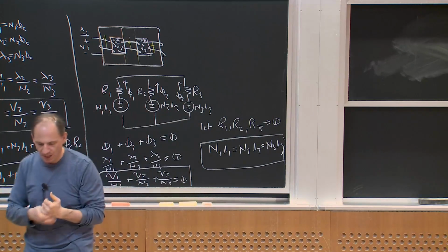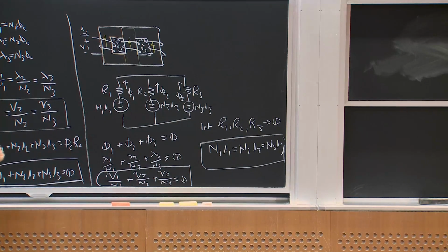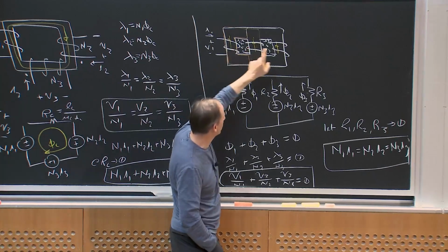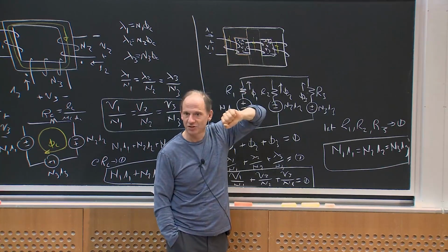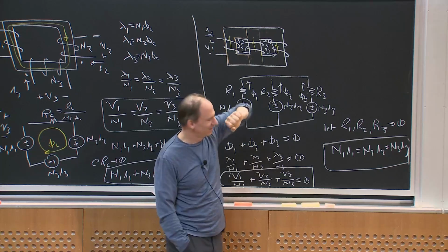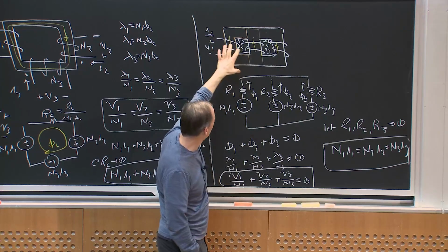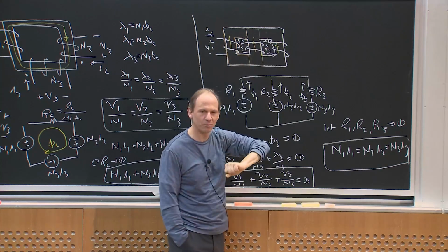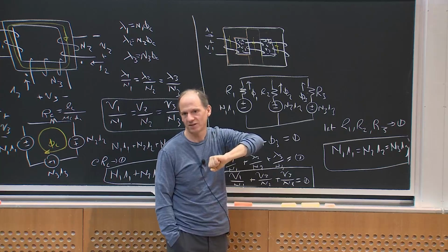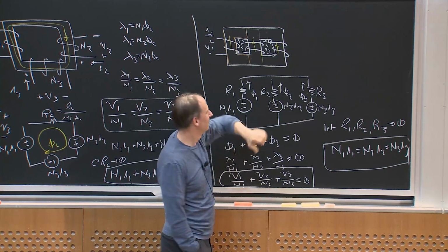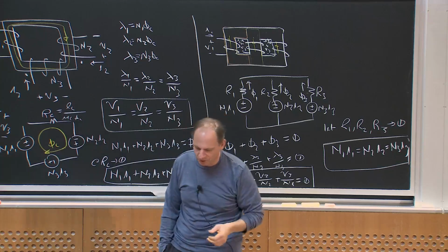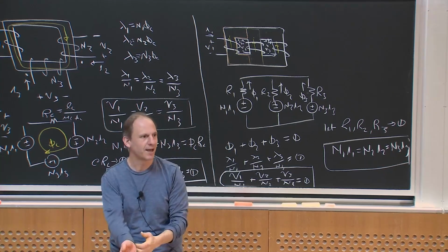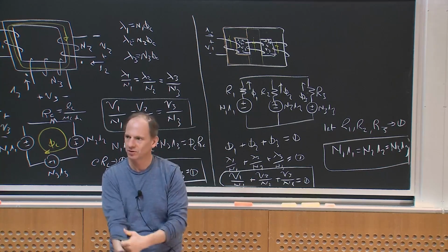Okay. I should say, by the way, however, notice that because there's no single flux path, there's not really a good way to indicate the dot convention here. There's something where the current into the winding scales, but we don't usually represent those with dots. People usually draw the structure or they do something else. There's not a really perfect, widely accepted schematic relationship between those. Okay.